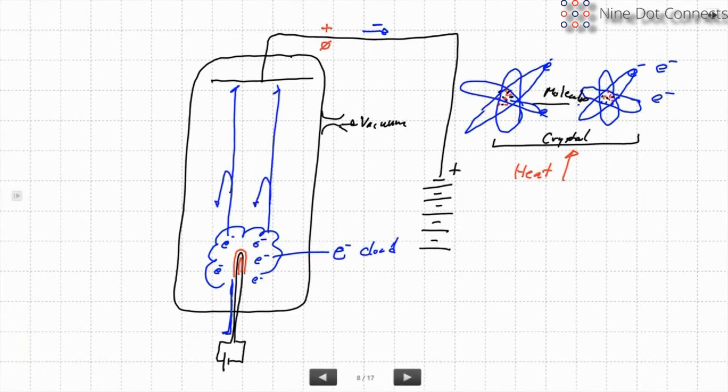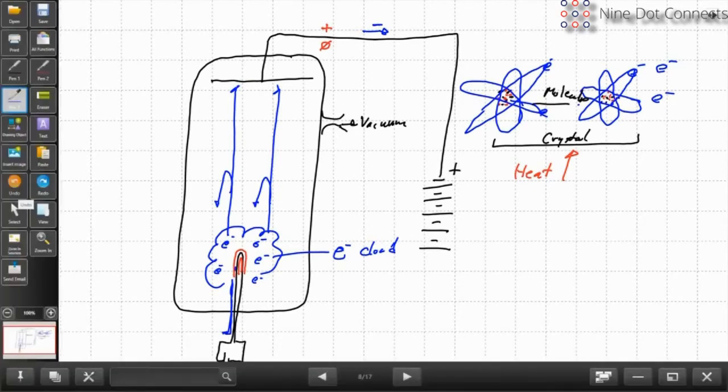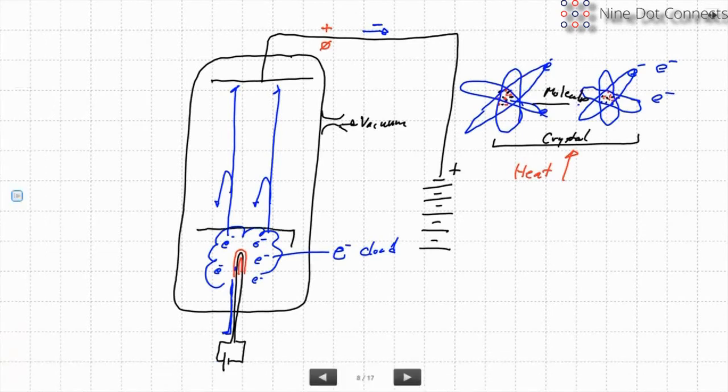And this turns out to work very, very well. This is a simple vacuum tube rectifier. Later on, they found that they could do some things very nicely. For example, they found that they needed some kind of resistance wire in the heater, so they could isolate everything by running the heater independent of the metal that was actually emitting the electrons. So they added something called a cathode, and the cathode was usually tied to ground.